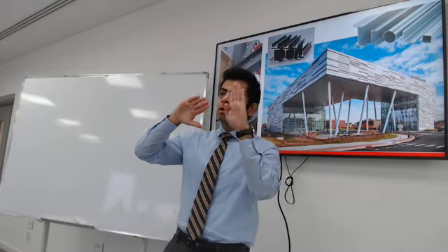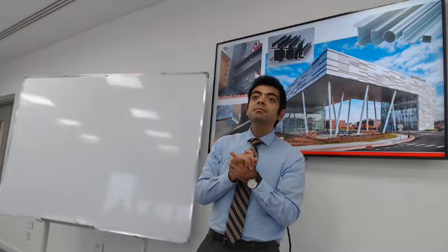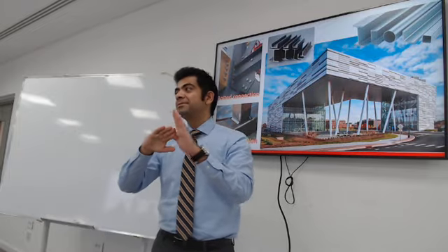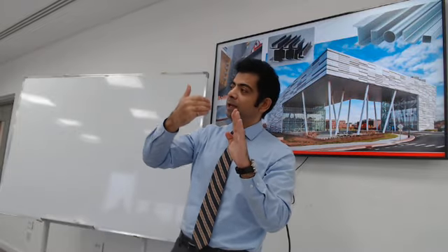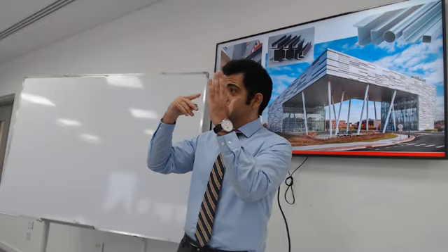How do you connect a column with a beam? You're absolutely right. Anyone can think how to connect a column with a beam? Any thoughts? Can I get any contributions, ideas how to connect a column with a beam? Plates at the end of the beam. At the end of the beam, you put a plate. Yes, with some holes. With some holes. Yes, for the holes, maybe they are put together if it's fixed or Yes, so you design the connection, fixed or pinned. Yes. And then what do you do with the column? Holes in the column, align the holes and bolt them?